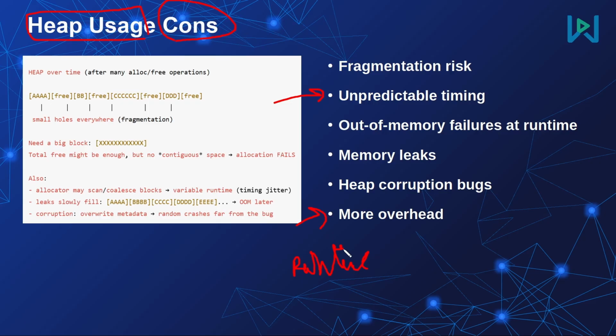The use of those C function APIs to maintain this allocation and the deallocation of the different sections within our heap memory will introduce, of course, certain overhead and unpredictable timing, especially if this is associated with cache memory.